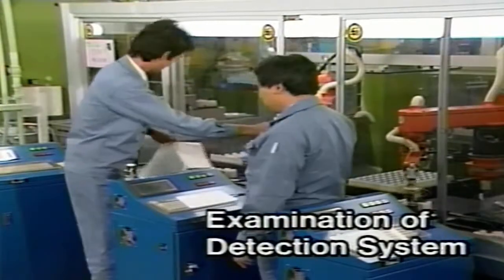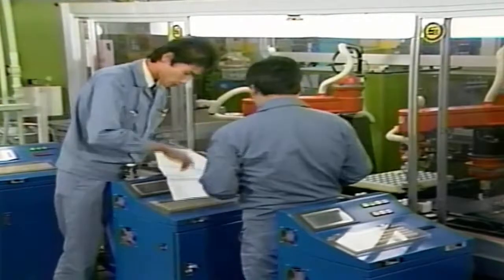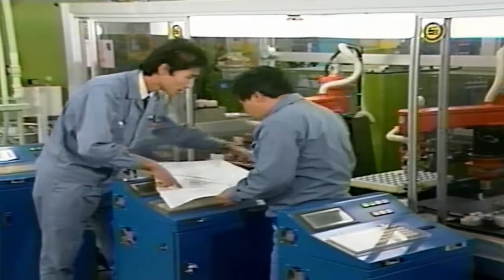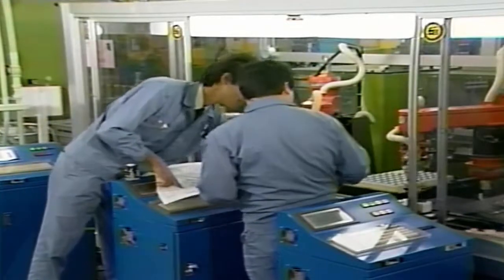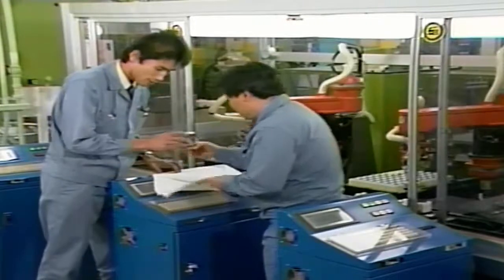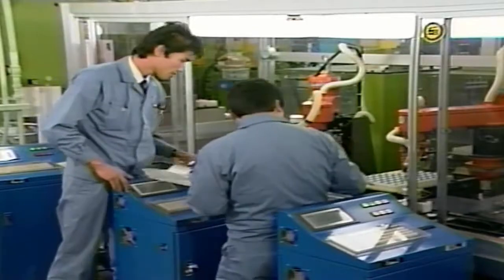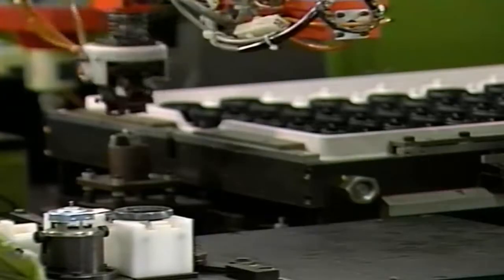There are 2 methods of approach towards improvements. The first is examining the detection system. Are there any problems with the position or ability of the sensors or the whole system itself? Where are the weak design points? Improving detection systems means that defects are detected earlier and short stoppages needn't occur.